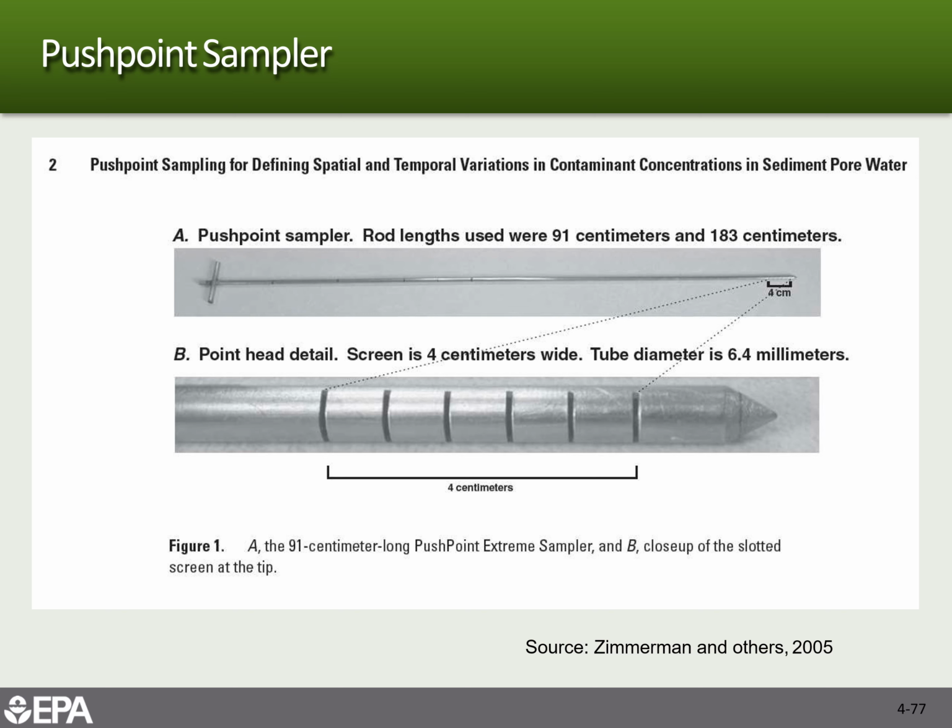And then you can put some tubing down this probe and collect a water sample from the transition zone in the sediments adjacent to a lake or in a creek. It's a really simple way to get depth-specific data. And it really all depends on how far down you push it. If you wanted to get a 20, 40, 60, 80 centimeter sample, you certainly can.